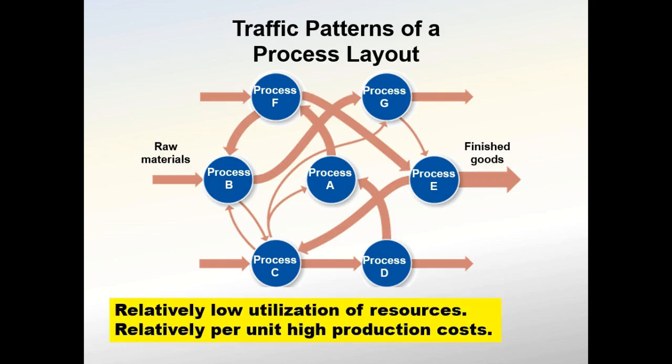And since process layouts usually do not require large amounts of capital to purchase high volume, specialized equipment, and are better able to cope with changing and uncertain demand, startup companies favor them. However, a process layout produces a low volume of customized product, creating inefficiency. So specifically, process layouts suffer these following 4 limitations.